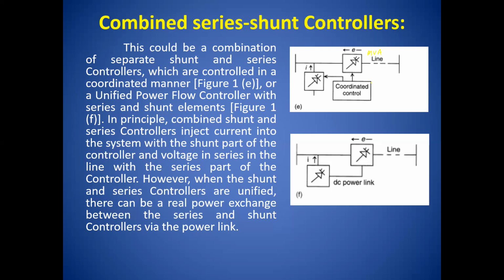This is the one. Second is that the series controller deals with reactive and active power both. So it is again a big advantage. And the MVA size of the series controller is smaller. These are some important points to consider while selecting the different types of FACTS controller.